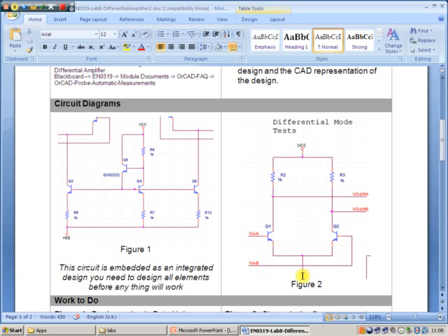You probably found a value of common mode rejection ratio from the previous lab, ballpark 40-50 dBs. We're now going to improve that. If we look at Figure 1, we're going to build a beta helper current reference cell and then put a current mirror in the outputs of the two differentials on our circuit.